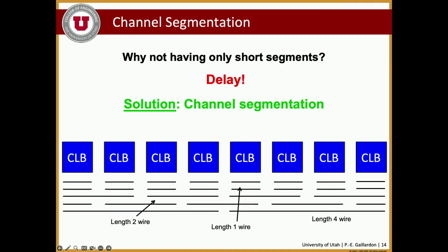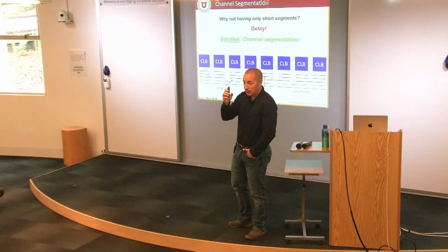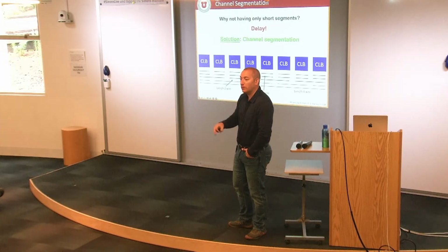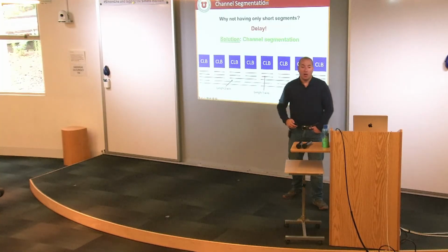Yes? So the CLBs are clocked, is that right? The CLBs will contain the logic elements and they can be purely combinational or sequential. And what about these switching blocks, no clock? No clock. I see, thank you. No clock, just signal routing, right?